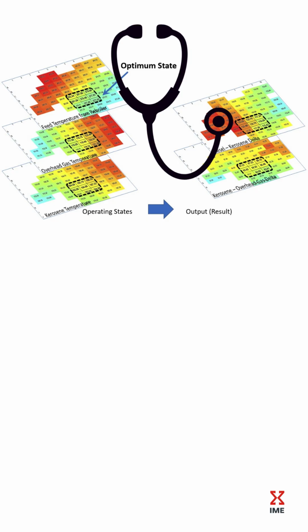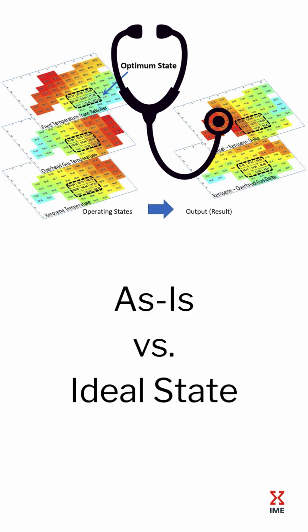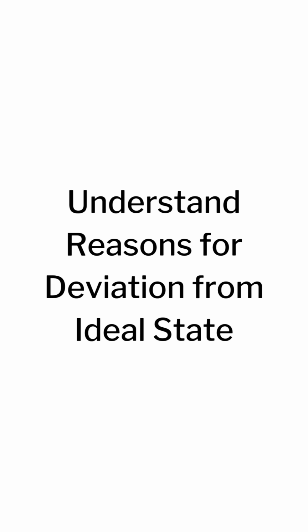Let us discuss time in-state as a diagnostic tool. The diagnostic side of time in-state is all about using historical data to understand and manage risks tied to the operational state of assets. When applied as a diagnostic tool, it maps the as-is state of the plant and compares it with an ideal or benchmark state. This mapping reveals deviations, highlighting where performance losses occur, how they impact equipment life, and which areas present significant risks to stable operations. Through this historical analysis, the methodology can pinpoint the sources of deviations and assess their impact on production quality, energy usage, and throughput.